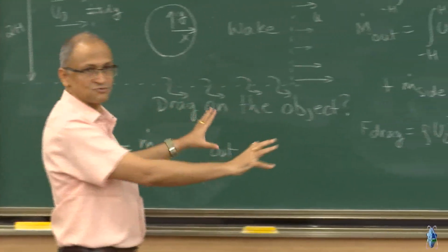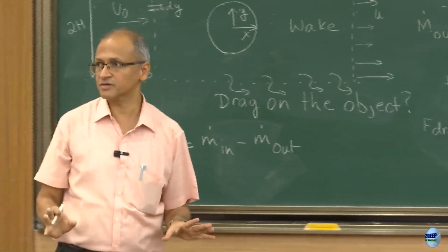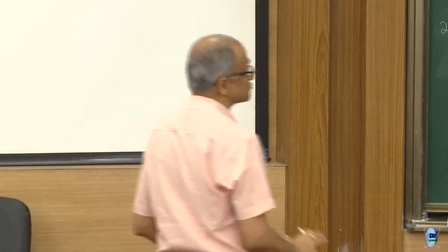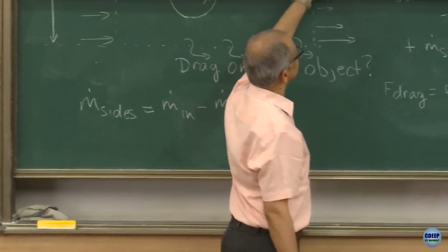Just remember, there is nothing wrong with this equation. We have said that these are very generic equations. There has been no assumption that we have made. So there is absolutely no issue using these equations even for that problem. The only thing is that if everything is time varying, then you have to be more careful and apply it with a lot more care. You cannot say that this momentum term we just neglected.